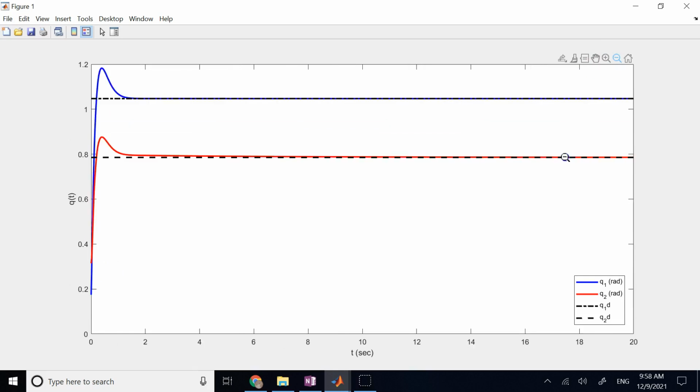So you see they are adapting very well. Although I use the PID control and everything, and although it's still set point tracking, the desired values are constant, the steady state error is not perfectly 0, but it's so small. When it's 10 to the negative 3 or 4 radians, remember each radian is 57 degrees.